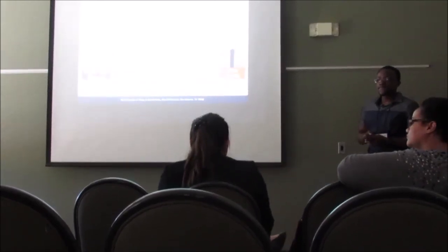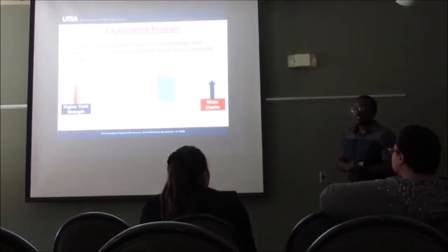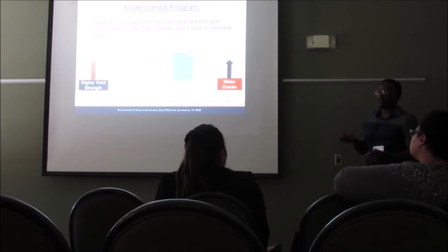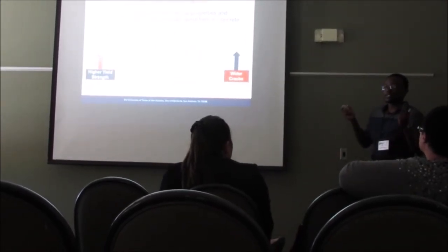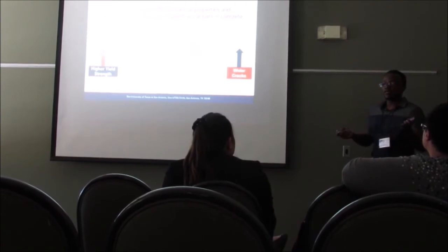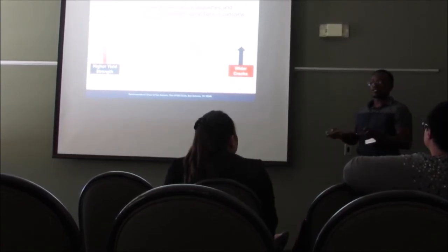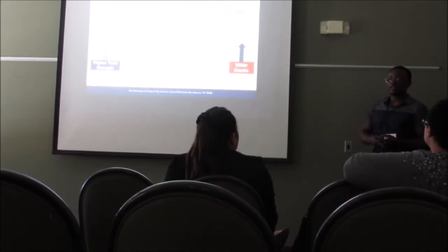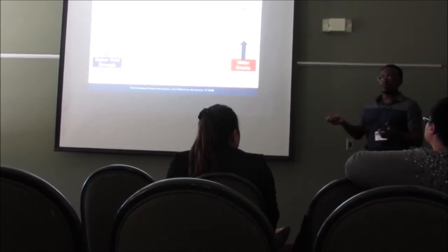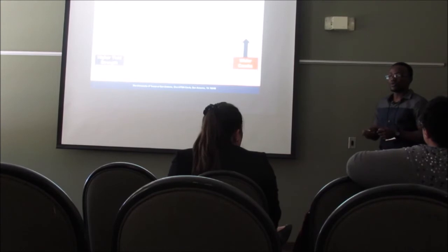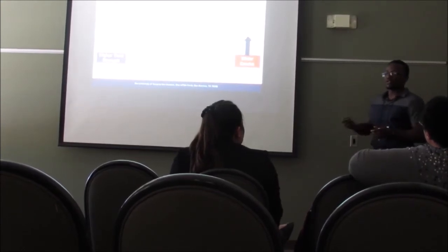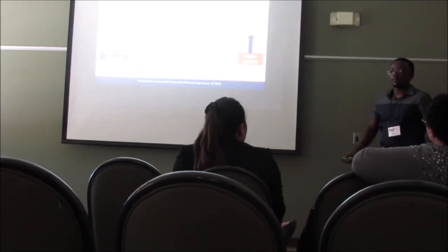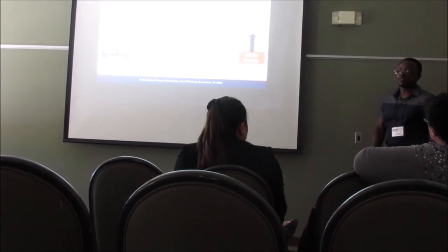What are other types of steel bars that you could use? The other type of steel bar, with the process of making high strength, microalloying is the most effective, but it's very expensive because you're adding different alloys like titanium and vanadium to increase the strength. That's why people use the cold rolling method, because all you need is the rollers to do it. But different methods of making steel is usually just adding carbon into the iron ore, and that's how the production of steel has been made throughout the years.